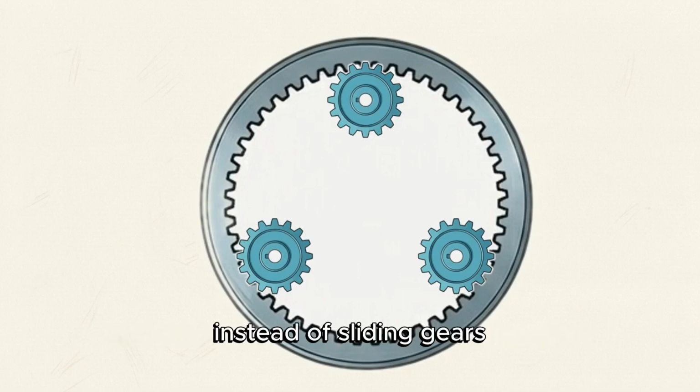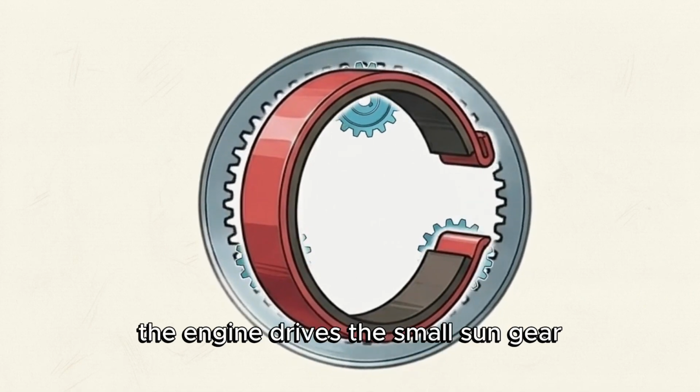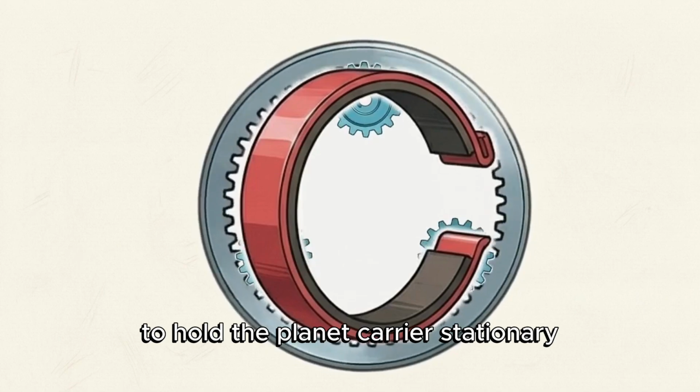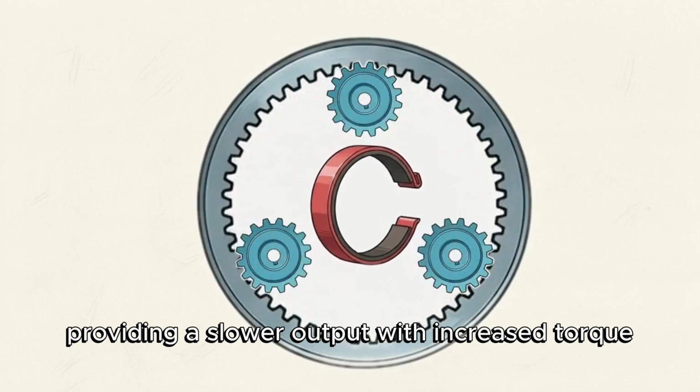Instead of sliding gears, ratios are changed by holding one component stationary while driving another. In first gear, the engine drives the small sun gear. A brake band clamps down to hold the planet carrier stationary. This forces the outer ring gear to rotate, providing a slower output with increased torque.